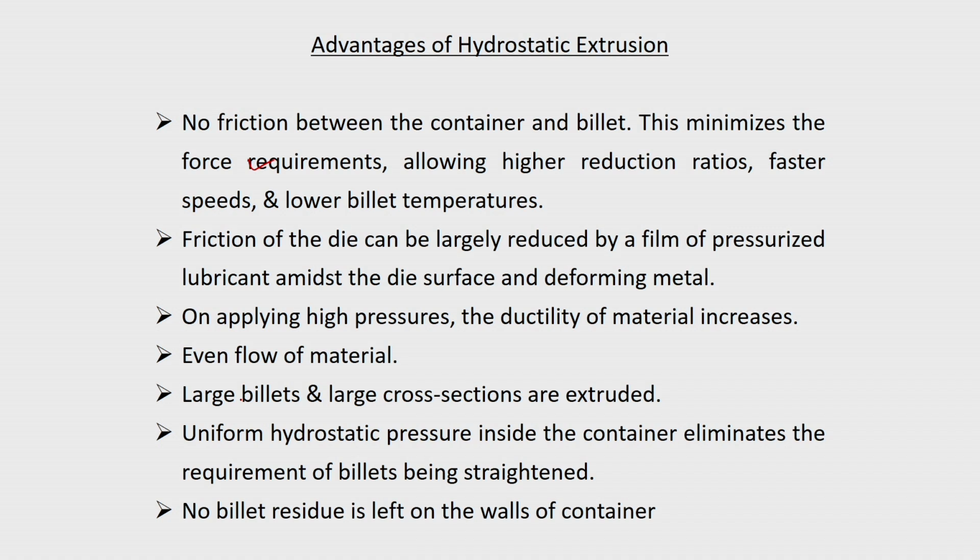And uniform hydrostatic pressure inside the container eliminates the requirement of billets being straightened. That is another advantage. So, you do not need to machine the billet to get a uniform cross section across the billet length. So, that is not required in this. Because of the hydrostatic pressure, this eliminates that need, and so that is one advantage. No billet residue is left on the walls of the container. This is another advantage which you are getting with the hydrostatic extrusion.